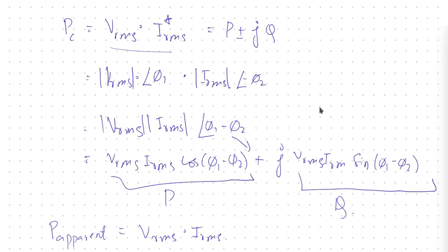One more thing to be kept in mind is when you are taking power of an element, say a resistor, with I and V, the power is Vrms Irms times cos phi, where phi is always the relative phase difference of these vectors I and V, and phi is always the angle relative to V, and it's not any other difference.